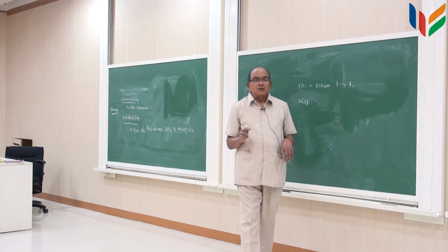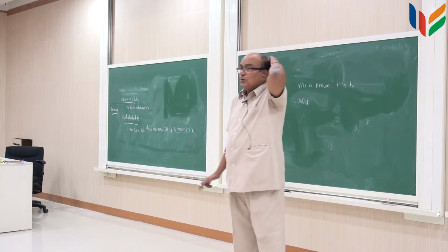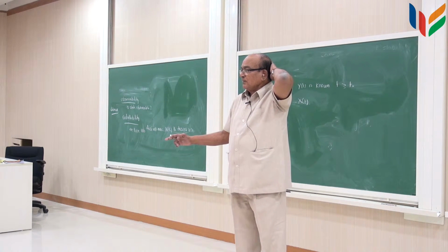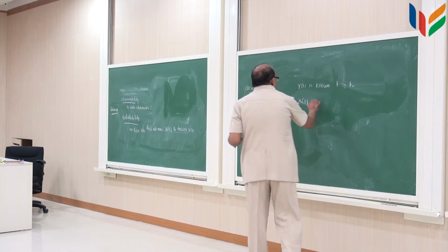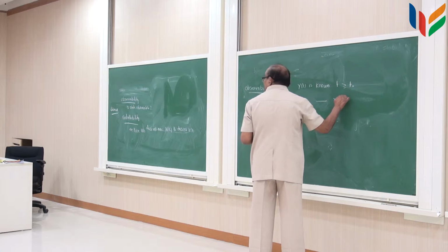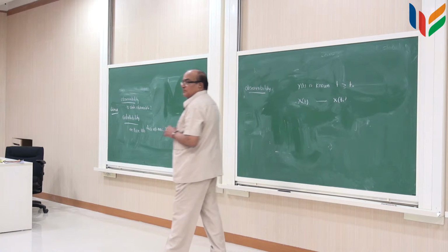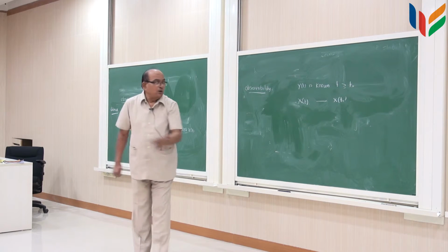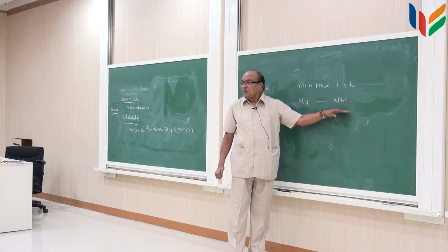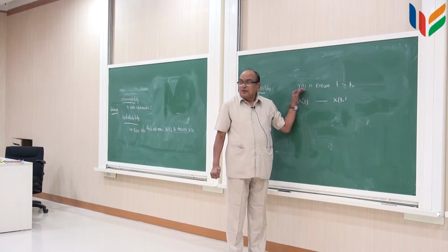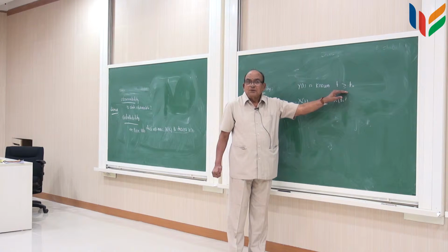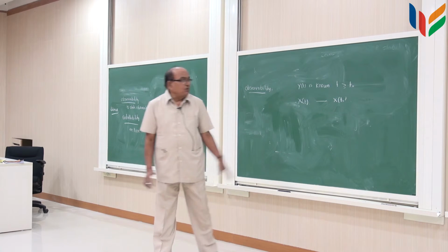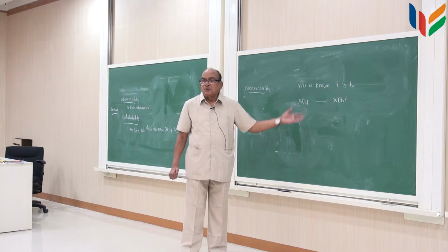From the definition of state vector, we said, given the inputs and the initial state, x of t is uniquely defined, right. So, it is enough to know what is x of t0, because once x of t0 is known and inputs are known, I know x of t also. So, knowing x of t is as good as knowing x of t0. So, the question is, given y of t for t greater than t0, can I find x of t0 from that information? If x of t0 is known, x of t can be found out by the transition matrix.